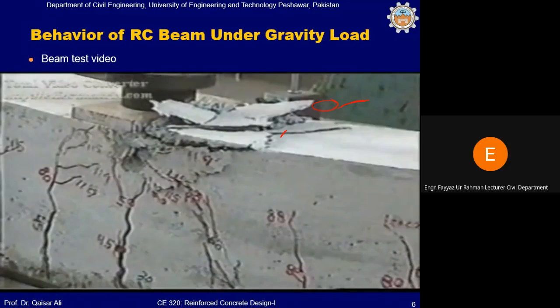Okay sir. The compression capacity can be increased even with steel. In a doubly reinforced beam we will study in detail how to improve the compression capacity of the beam, and for that you can provide even steel at the top. However, since we are discussing here the analysis of singly reinforced concrete section, that is why in this beam the reinforcement will be only provided in the tensile portion, that is in the bottom in this case.